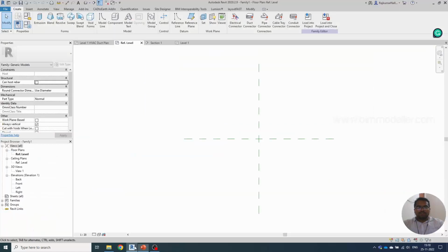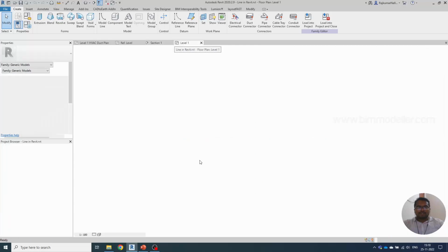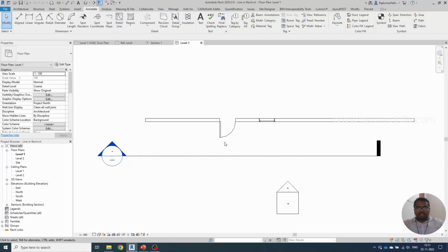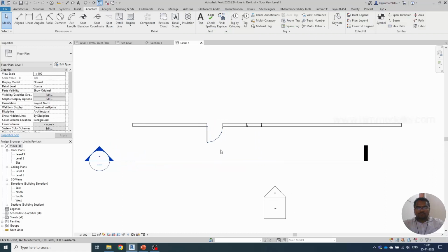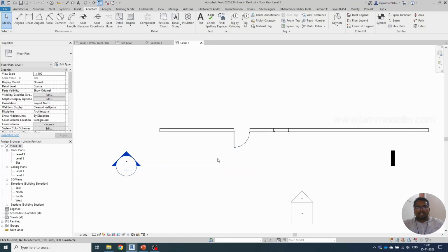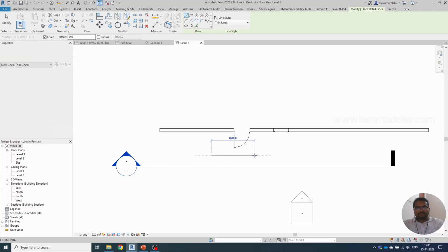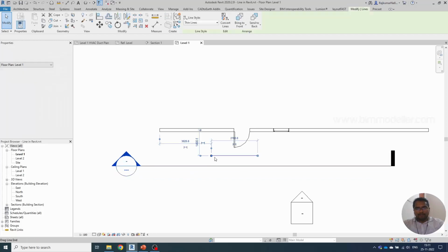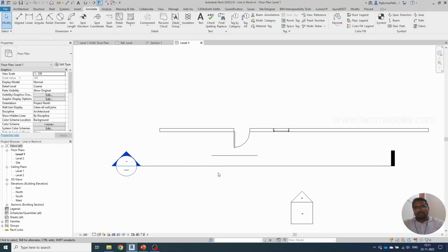With that, let me show you the example. I have here a project which is in the floor plan. I have placed a door. If you see, the door will have a symbol in its front view showing how to open this element, and if you draw a line in this place, a normal annotation detail line, the line will not be visible in any parallel views. It will not be visible in the next levels because that's a parallel view.